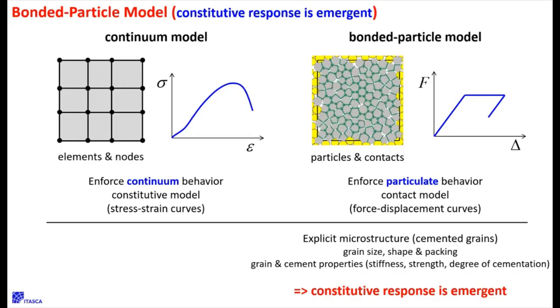Yes, what you're talking about is exactly this concept, right? The fact that the bonded particle system lets you put in a microstructure and gives you a stress-strain response. And that can be a very realistic and complicated stress-strain response. And this is a way, as you're saying, of hooking that into another type of continuum model, shall we say, MPM. Yes, good.